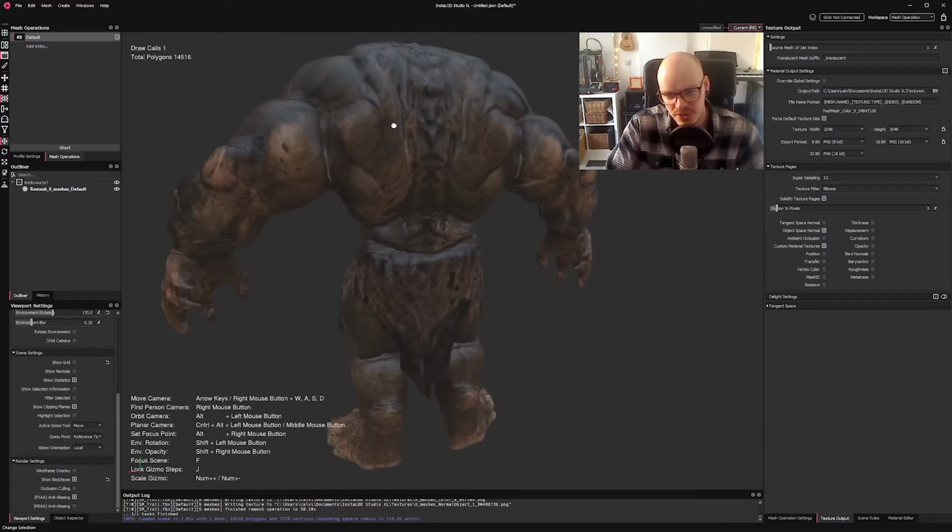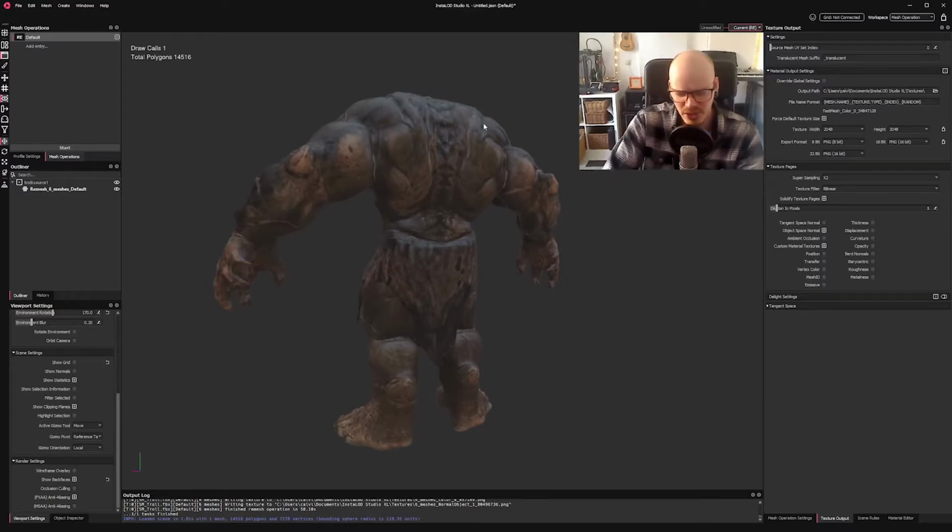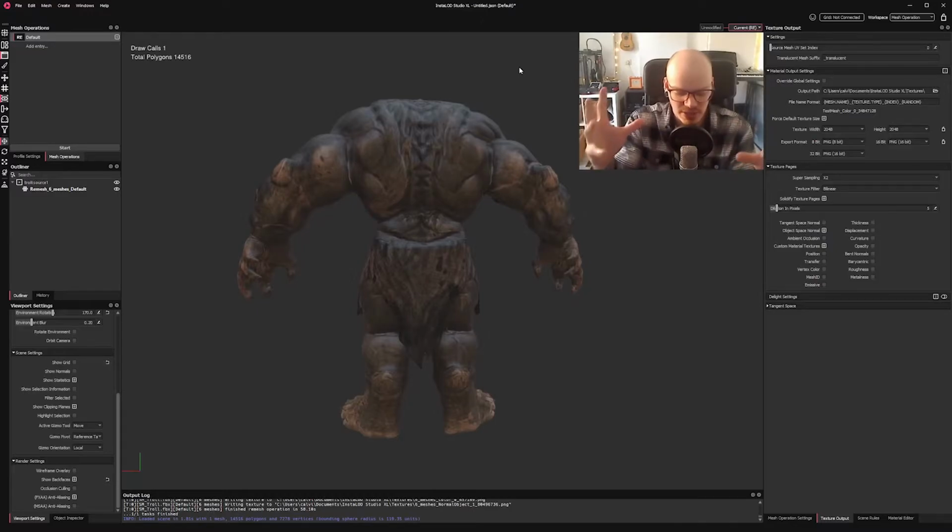And just to put some perspective into this, if we were to take the input tangent space normal map and just project it onto this new mesh, it would not work. It would never look good because tangent space normal maps are really finicky. If we just remove or change a single polygon on that model, the normal map is completely broken.